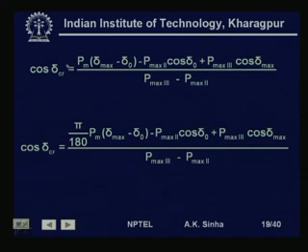Now, this angle that we will get from here will be in terms of radians. If we are using degrees, then we will have to multiply it with 180 by pi. So, for cos delta critical, in that case, if we are using delta max and delta 0 all these as degrees, then we have to convert them into radians.